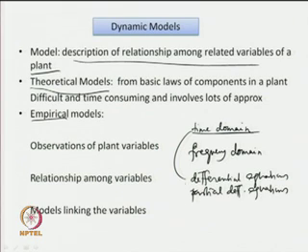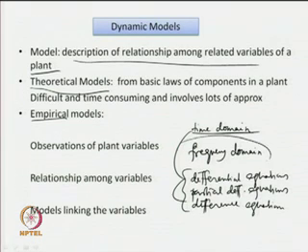Again, in digital form the model is available as a difference equation. So, all these forms of representation of a model of a system are in time domain. In frequency domain, generally the models are expressed in the form of transfer function. Some assumed form of transfer functions are taken to represent the dynamics of a process behavior.